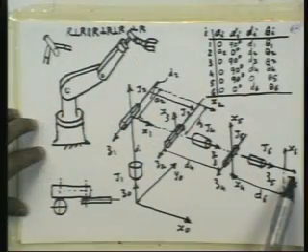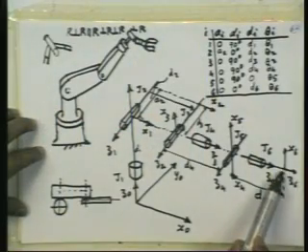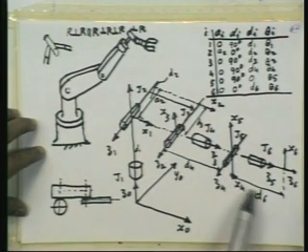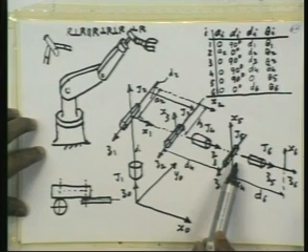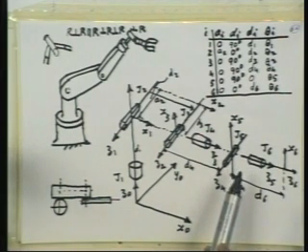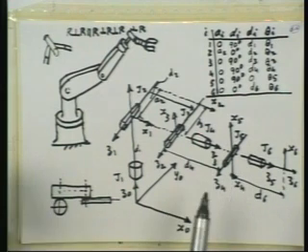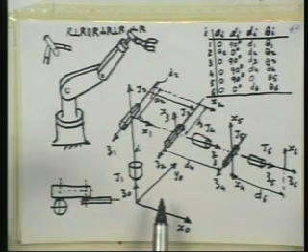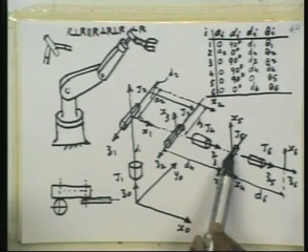If you look at the end effector x6, y6, z6, and if you look along the z axis backwards, this particular point is at the distance d6 on the z axis. It is nothing but the point 0 0 minus d6 on the end effector reference frame, right. So then the position of this particular point in the global reference frame can be very easily obtained, because we know the end effector reference frame position and orientation, right. So the global position of this point is very easily obtained, fine.